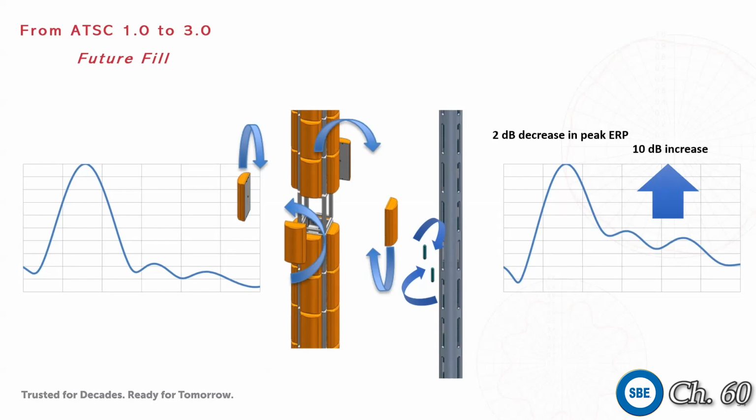This is really beneficial to you because it is a very small amount of downtime. Especially for a slotted coaxial, the time it takes to have somebody go up is similar to changing a light bulb up there. Also, there's no complicated Rube Goldberg contraption that gets bolted onto this thing in the middle of the air. So your VSWR and all of these characteristics remain exactly the same. And so once they're up, they switch it and you're back on the air.